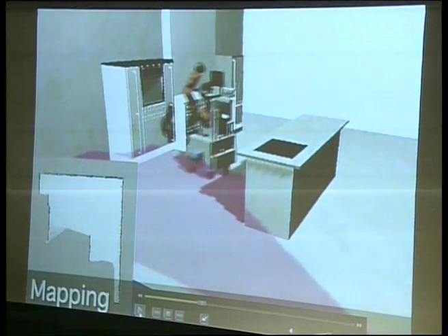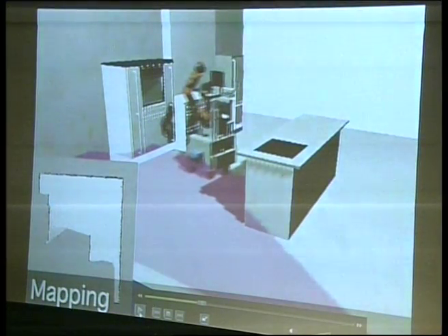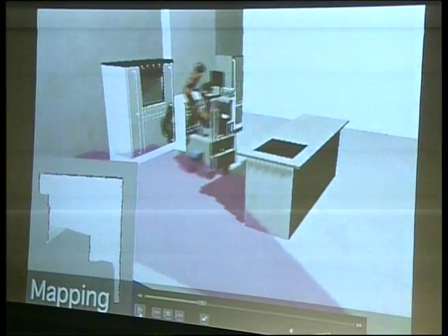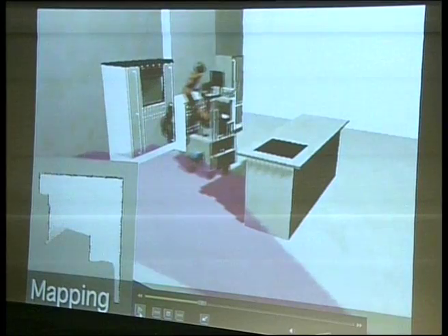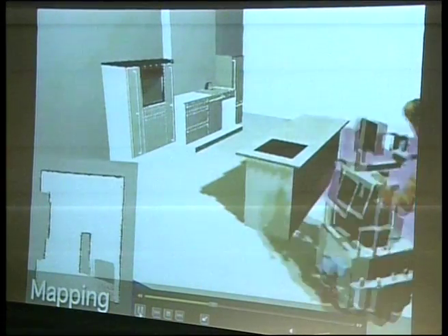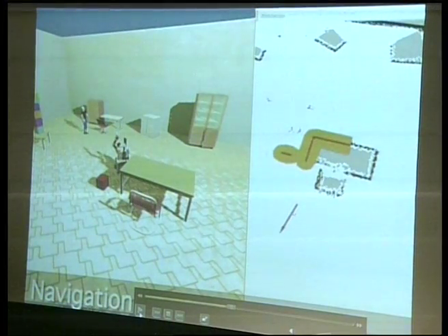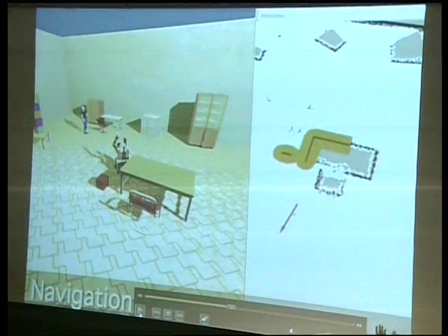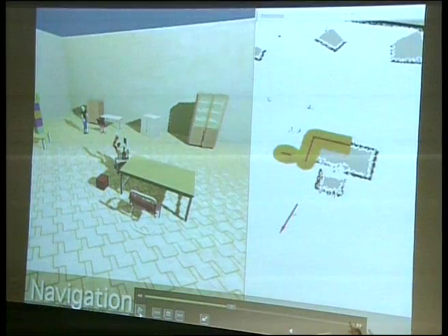It's 2D only. It's measured at the level of this plane, which is displayed in pink. That's a plane where a set of lasers are scanning everything around. They just identify obstacles, and that's translated into a 2D map of the environment, where you can see where there is a table. Here, to the right, we have already that map. It has already been created, and now the robot wants to go to where that red arrow is.